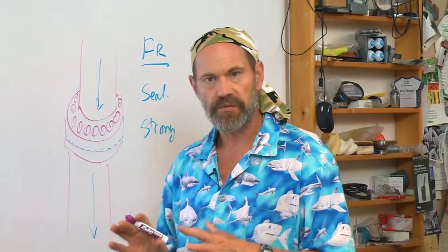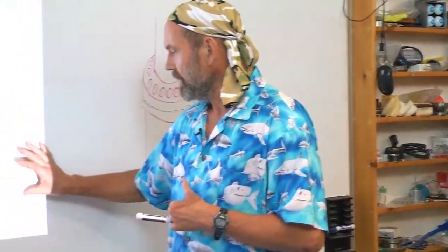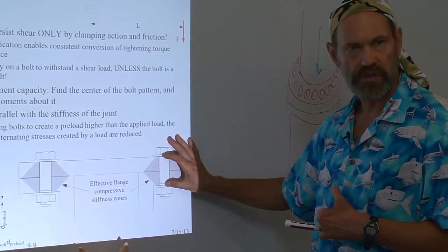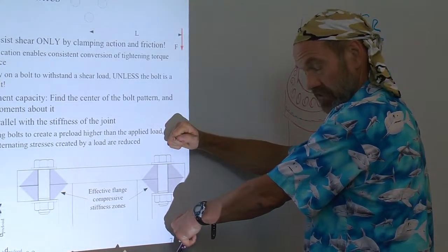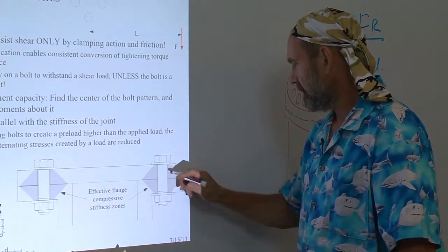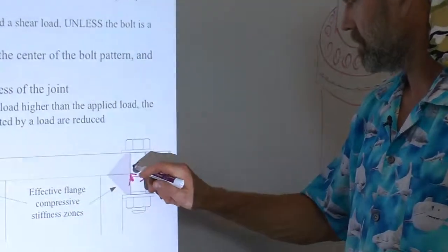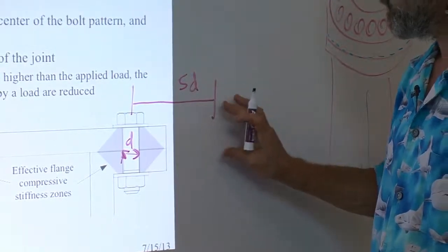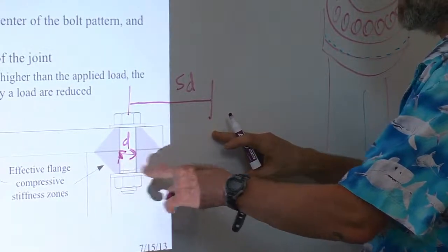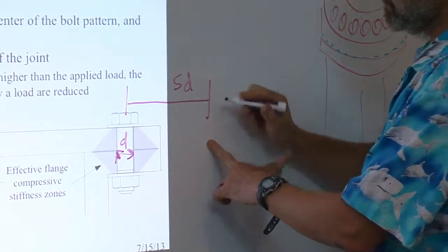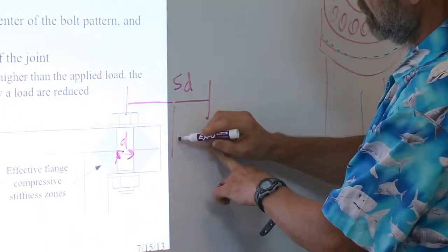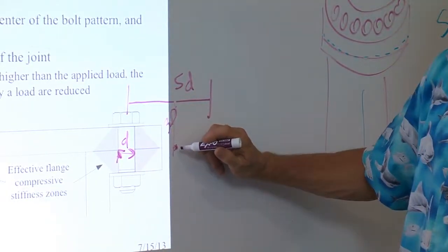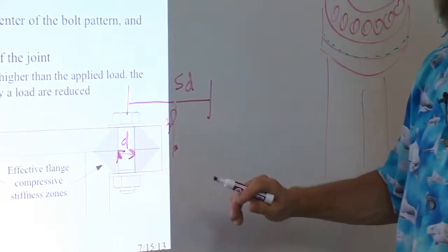And remember St. Venant's principle from Topic 3. Now look at the cross-section through a bolted joint and consider when you push on that joint by tightening the bolt, and hence essentially squeezing the joint. If this bolt diameter is D, when I go 5D away from the joint, no matter how hard I tighten that bolt, I really won't be able to detect it over here. Come away about 3D, and I still really won't feel it, but I may, it depends on the thickness of the joint.